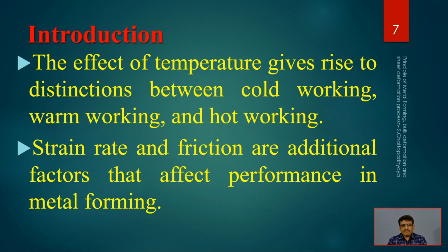So the effect of temperature gives rise to the distinction that we have already discussed, between cold working, warm working and hot working. Cold working is at room temperature, slightly elevated temperature is warm working, and beyond the recrystallization temperature is hot working. And there is also another very important parameter, strain rate.